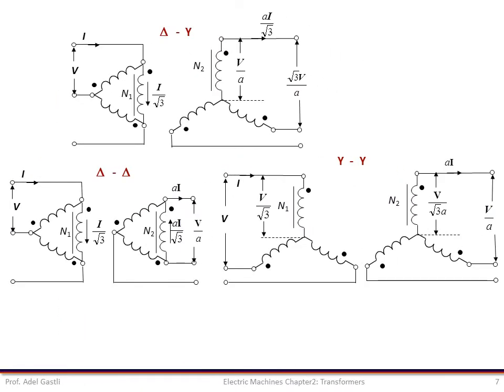Other possible connections are also shown in this slide. It may be noted that for all possible connections, the total kVA of the three-phase transformer is shared equally by each phase transformer. However, the voltage and current ratings of each transformer depend on the connection used.